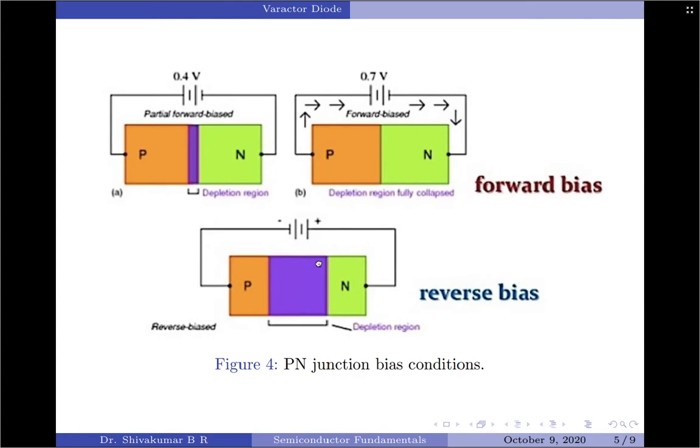So, if we need to increase the capacitance of a Varactor diode, the reverse bias voltage should be decreased. It causes the width of depletion layer to decrease, resulting in higher capacitance. Similarly, increasing the reverse bias voltage should decrease the capacitance. This ability to get different values of capacitances just by changing the voltage applied is the biggest advantage of a Varactor diode when compared with a normal variable capacitor.